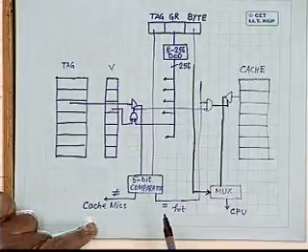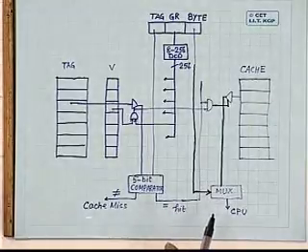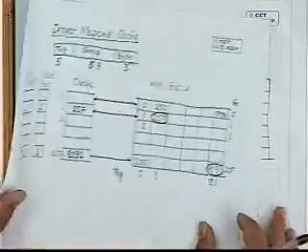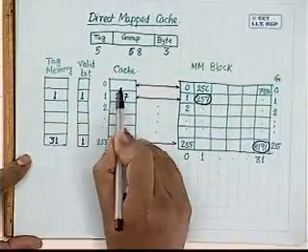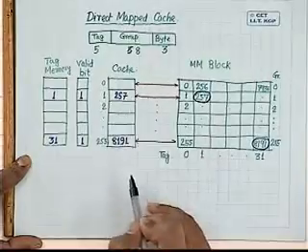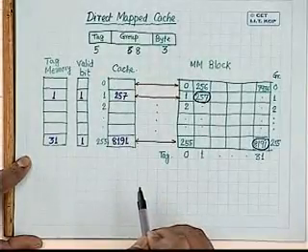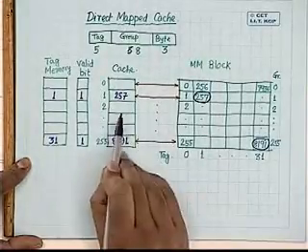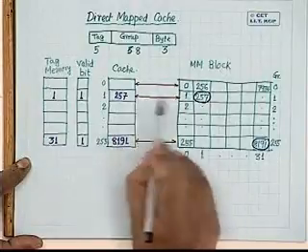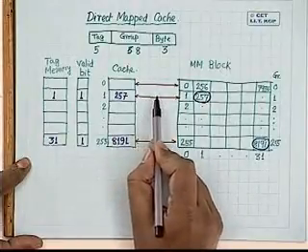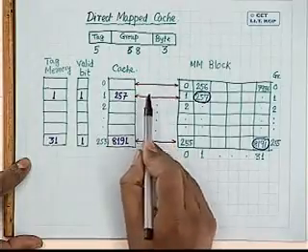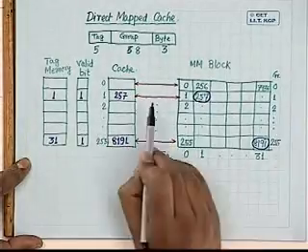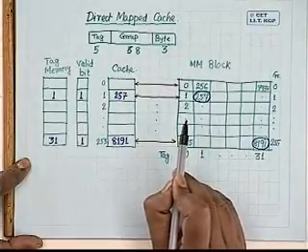But what is the disadvantage? Because in this particular case, you have specified that a particular block in the main memory can only go to one cache line. It cannot go anywhere else. So the number of cache misses may increase, or the number of data being taken out of the cache memory or put in the cache memory will also increase.